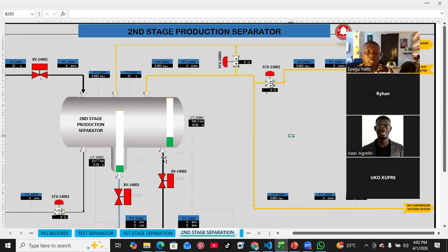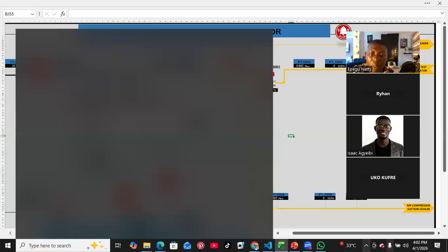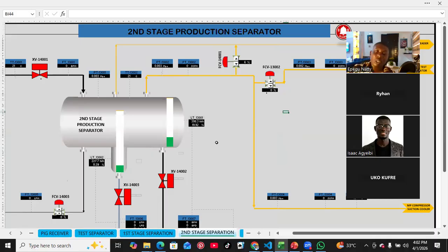So the question is, do you bypass the alarm, right? And what are the procedures to bypass the alarm? Now, the first instance, you can mute or shelve that particular alarm. Whenever the alarm rings, you just mute it, right? That is what you can do. But is that also okay? Or, let's imagine that the transmitter at that particular region is bad, and then they need to order a new one, right? So if it is something they can finish within a day, you can mute it, and then you unmute it again.